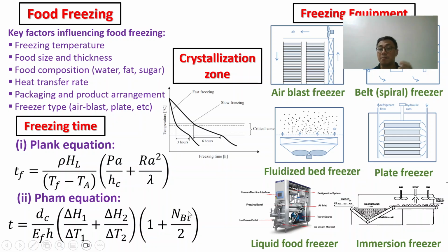The Biot number is very similar to the Nusselt number. The difference is that the Biot number is the ratio of the convective heat transfer coefficient times the characteristic length to the thermal conductivity of the solid. In the Nusselt number, the thermal conductivity is for the fluid. So when we have these two equations, we can predict the freezing time with all the parameters.